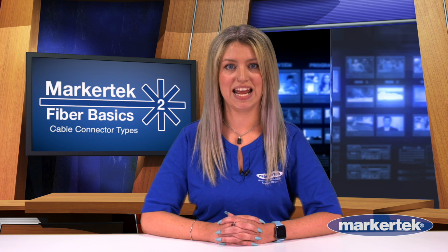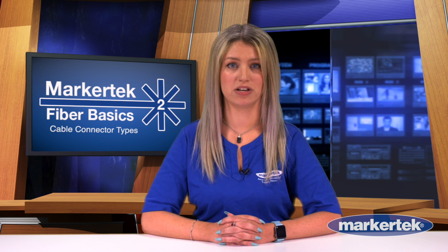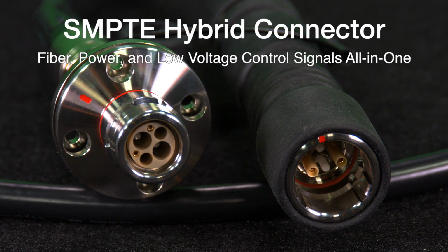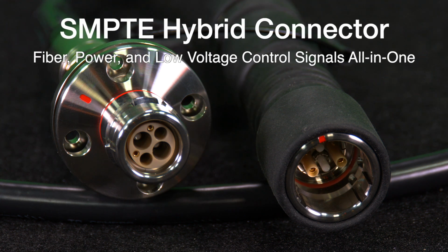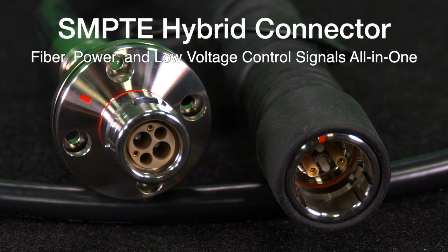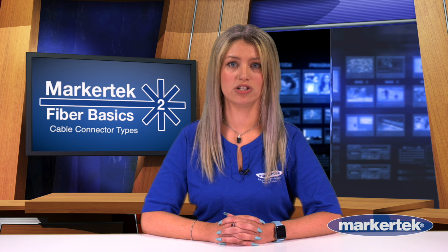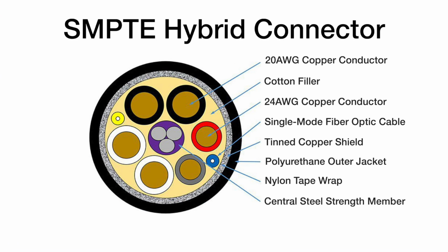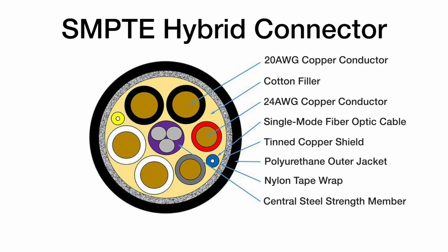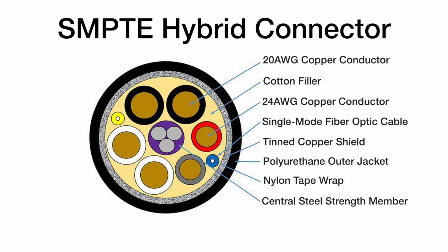In broadcast and AV installs, and especially in military applications, there are many specialty connectors. Here is what is known as the SMPTE hybrid connector. Lemo and Canare are the two more common brands in this space. These connectors are commonly used on broadcast video cameras and connected camera control units. The hybrid portion comes into play because the cable used for these connectors has a single-mode fiber jacketed with a set of copper conductors, which can carry signals like intercom, control, and power.